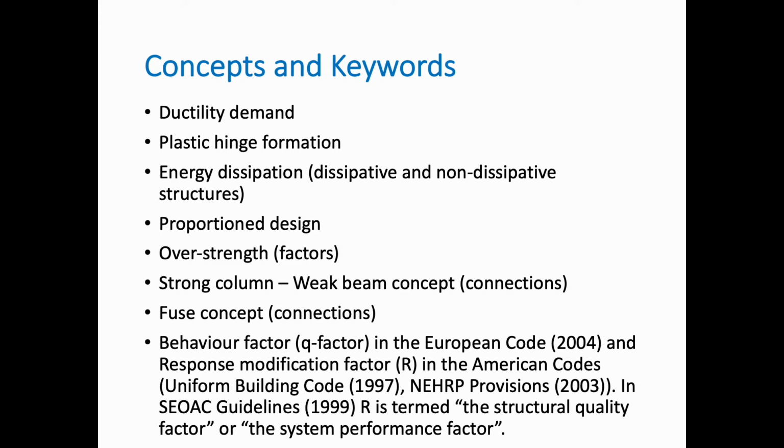And of course, the behavior factor Q for the European codes and the response modification factor R for the American codes is something that I will be using in this presentation, and on some occasions I will compare the European with the American standards so that you have a point of reference and that you can see what are the main differences when we design.